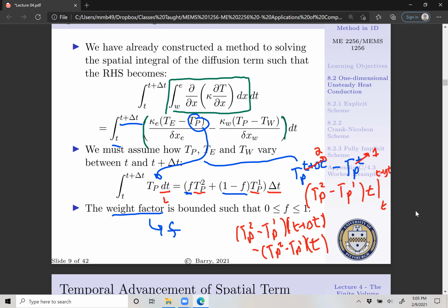But it's weird to think about that as you're solving your solution, you're using the data from your current time step to populate it. And this works quite well in a finite difference scheme. If you're using a backward difference, as you move through your domain, you can always pull the most recent values and proceed along. You can do it with the central differencing scheme too, except you have to solve your systems of equations simultaneously through matrix inversion. Doing a brute force for loop's not going to work.